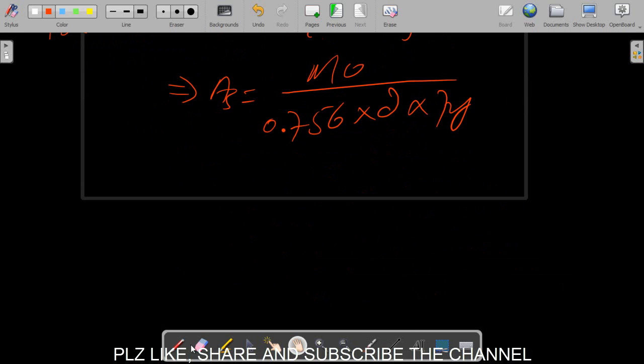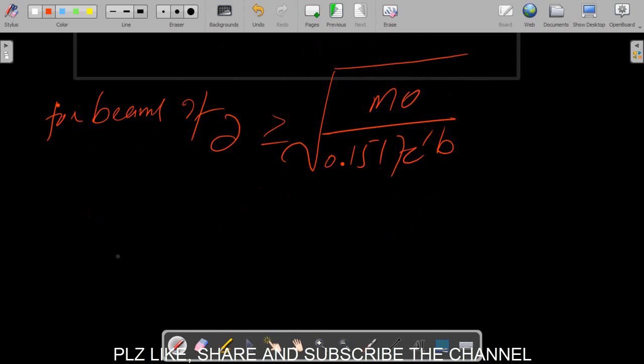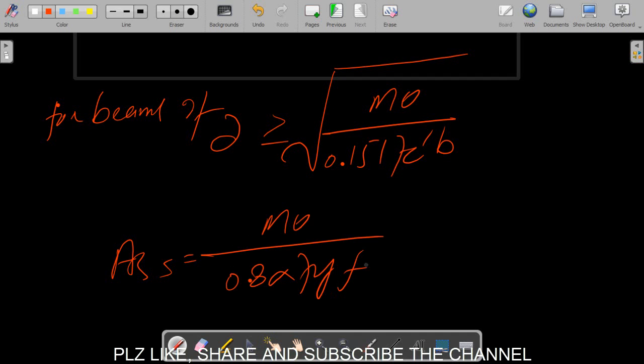This is approximate, right? And for the beam, if d is greater than or equal to Mu divided by 0.151 Fc prime into b, then the area of steel will be Mu divided by 0.8 times Fy into d. So this will give us the approximate method.